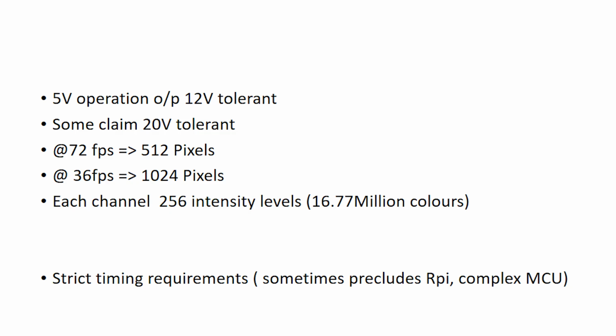So if you've got a circuit that's driving a string of NeoPixels, and it's halfway through putting the pulses out, and the Wi-Fi suddenly needs attention, or the screen needs a refresh, and the chip has to abandon you to go and do the screen refresh, then you'll lose the NeoPixel frame.